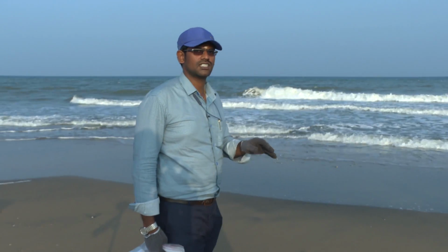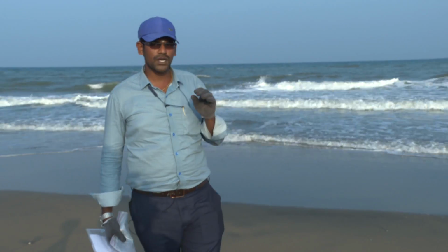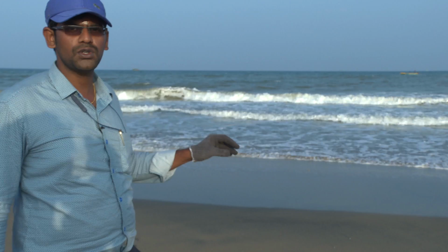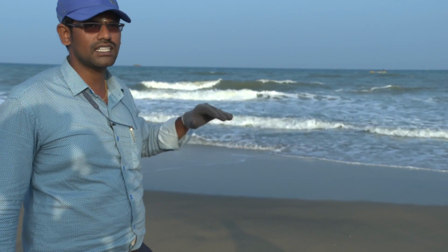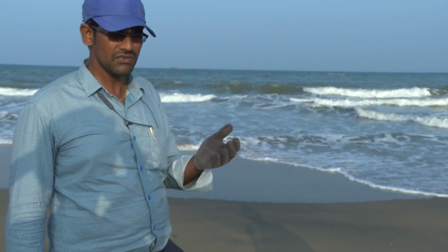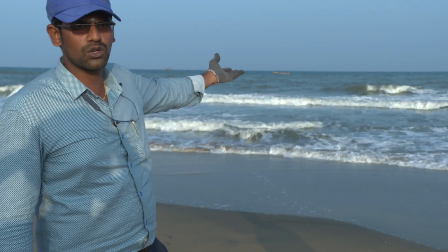Now we are going to collect onshore samples, that is, onshore samples at this berm and here at the shore. The purpose of collecting these onshore samples is for determining the gradation of the soil. Using the grain size analysis and specific gravity, we will see whether the soil is well graded or poorly graded, and differentiate the soil grades. This gradation and grain size distribution are needed for constructing coastal structures. So in our project we are collecting onshore and also offshore samples.